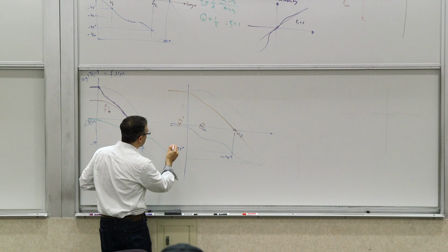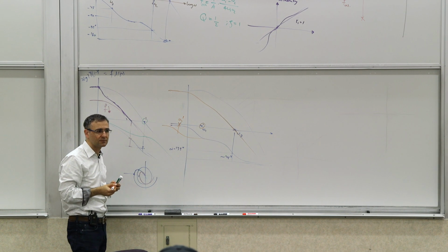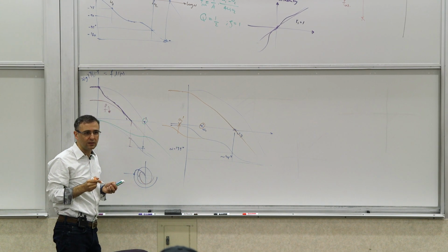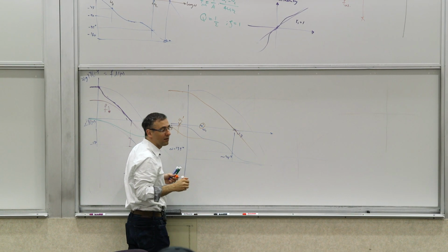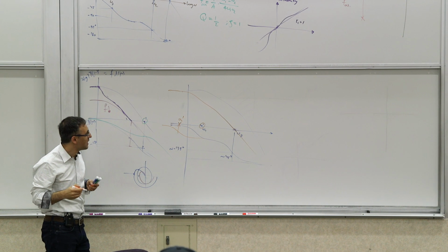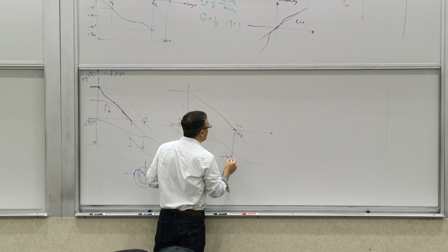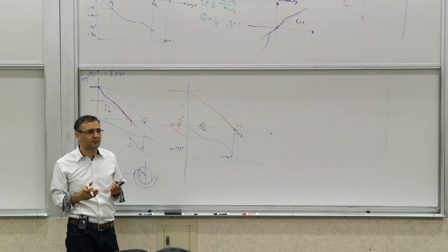Well, in the phase plot, of course, the phase contribution of this part will shift to the left, right? The amplitude starts dropping earlier. But as a result of dropping earlier, you start hitting omega 2, the unity frequency, at a lower frequency. So if I were to put this unity frequency around omega 2, I should expect to get roughly 45 degrees of phase margin.